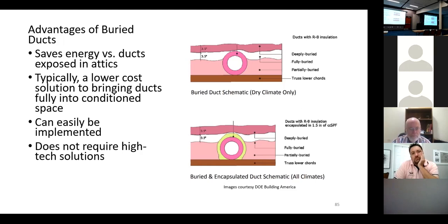We do get condensation. Now, flex duct that we see everywhere has a vapor barrier on it, but how often is that vapor barrier tight and complete? Hardly ever. So in humid climates, the code is now saying put your ducts in the insulation, but encapsulate them in closed cell foam, because that does away with that. It seals the air. We have more R-value, and we're not going to get condensation. In our climate, we don't have to do that, but spraying the foam, I know it's $1 an inch per square foot, seals the duct completely.